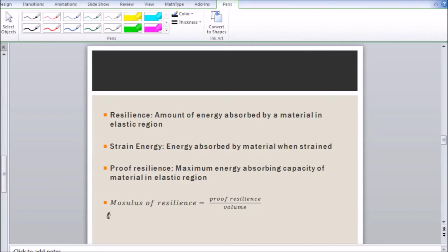Earlier I have already discussed that when a force is applied on any material, object or element, there will be a certain deformation, delta. As the force increases, the deformation increases. Under tensile and normal force, the deformation is a change in dimension, that is, length increasing or decreasing. If it is a shear force, the deformation is in the form of shape change, that is, distortion of the shape.